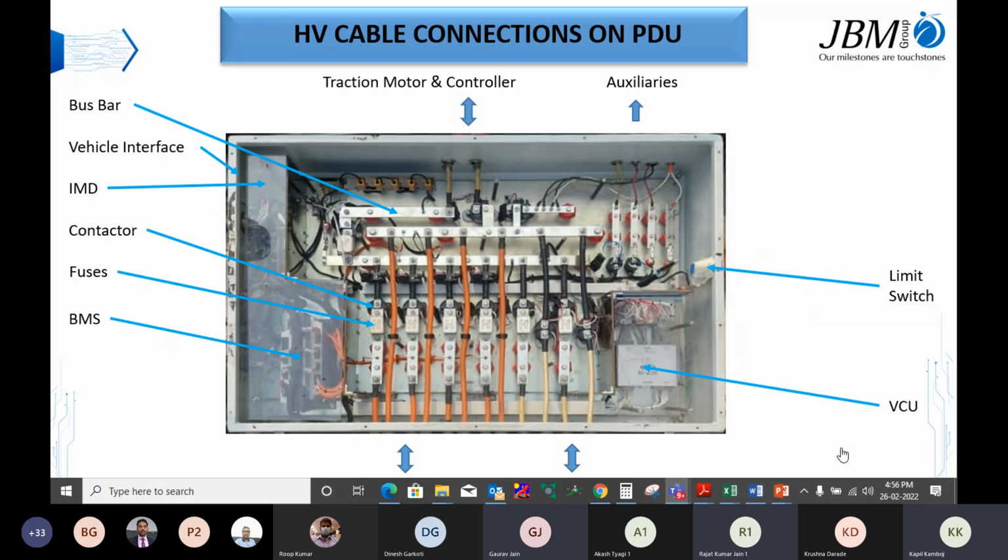Obviously, but instead of 2 sockets, 4, wait Rajat, wait. See, the charging socket has a capacity of 200 ampere. One charging socket, so you cannot go beyond that as of now. Some people are working on 300 as well, and liquid cooled charging for the bus at 500 as well, which is not in the SOP phase yet.